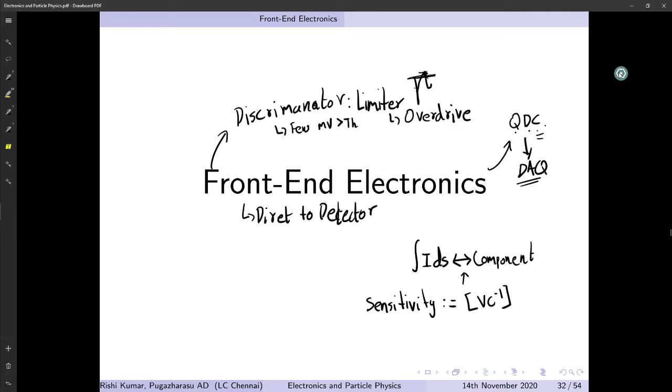And yet again, the important aspects are noise and sensitivity. Since we're also talking about a digital piece of electronics, your sampling rate and the number of bits are very important. There's a very interesting characteristic called resolution, which is basically the number of bits. And obviously you also have your conversion time. These are the factors that matter.